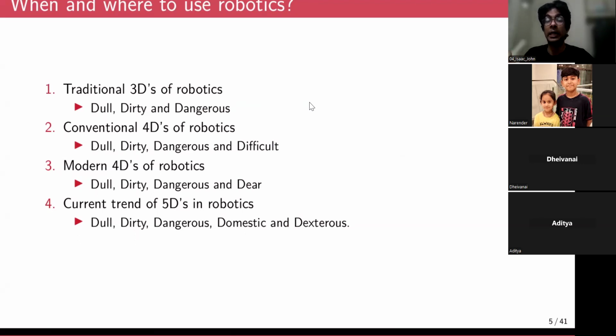But there are points that are not fully dexterous. One example is that if you fully stretch your arm, the point that you reach with your fully stretched arm, you can only reach with that single orientation. You cannot reach that point with any orientation. The same thing goes for the point when you fold your arm fully, because you can reach that folded point only in one orientation. So even though those points are reachable, they are not dexterous. Right. So that's what the word dexterous means basically.